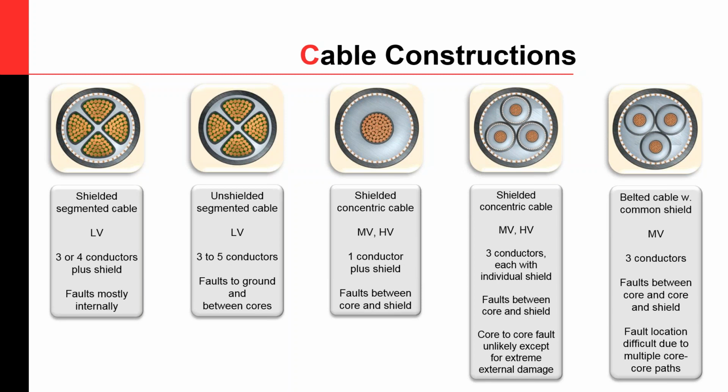The field is not symmetrical, so the stress is not distributed symmetrically. And here you can have various different scenarios also for the fault, which can be a phase-to-phase fault. But as I said, this is predominantly for the laminated cables, the PILC cables, and so this doesn't really apply for extruded cables.